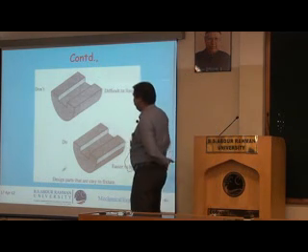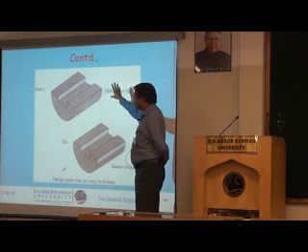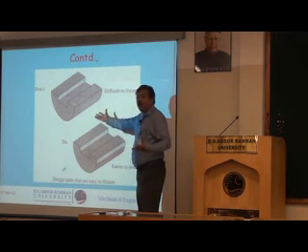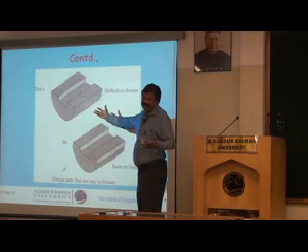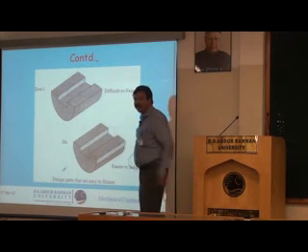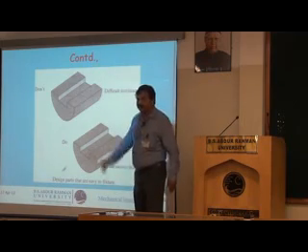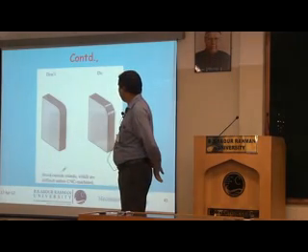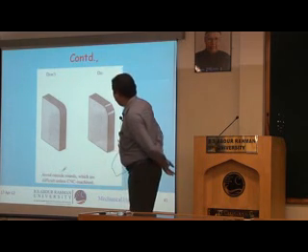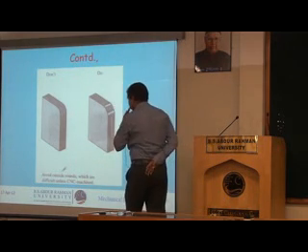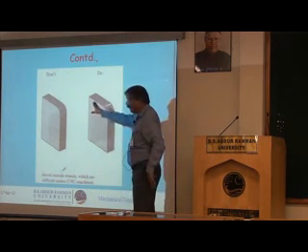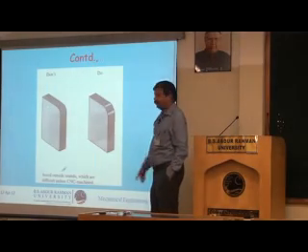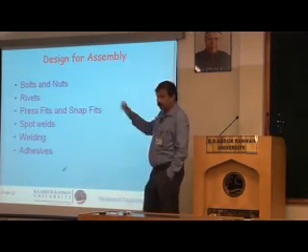So here, when you have a cylindrical surface, I don't have any reference. I cannot even hold it. I cannot have a fixture for this. So try to have some references. Have a flat surface here. It will be easy for me to reference it. Next slide. Don't provide outside rounds, which are very difficult to machine unless we have a CNC machine. Next slide. Now, go back.